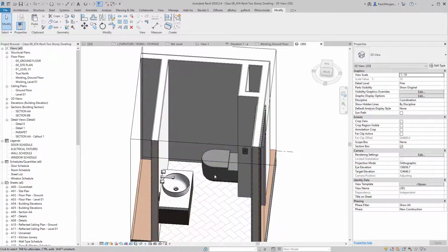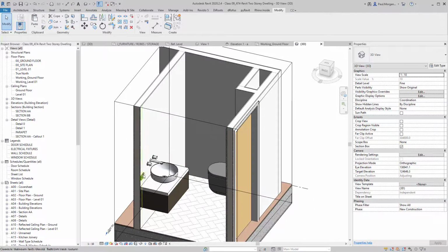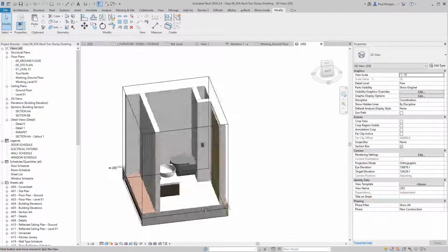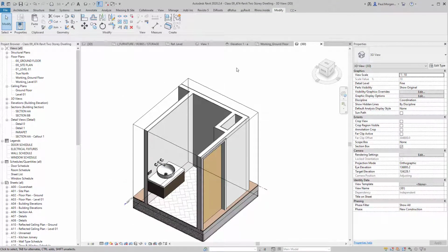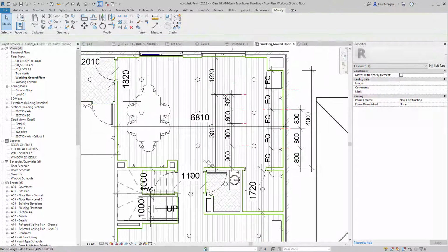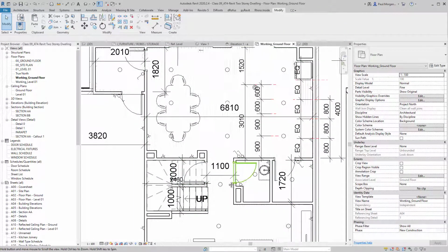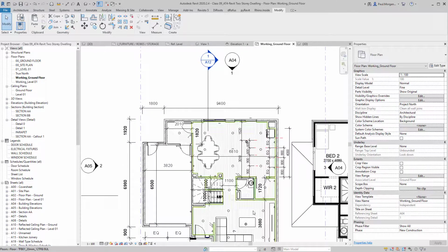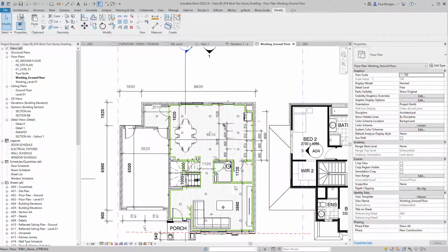Door opens, light switch, toilet, vanity. We can put a mirror in a little bit later, but that's our first casework model now done. So that's our vanity unit for in here. Now we can keep playing around with this. So modeling in place is really for more of your simplistic family. So that is a very simple family, but it does work for us.